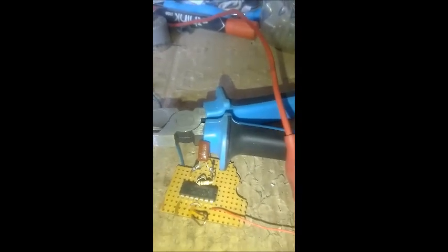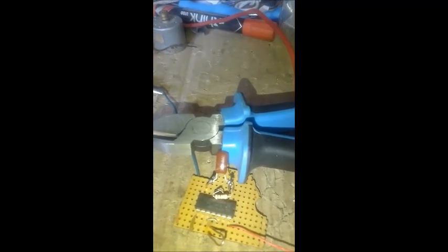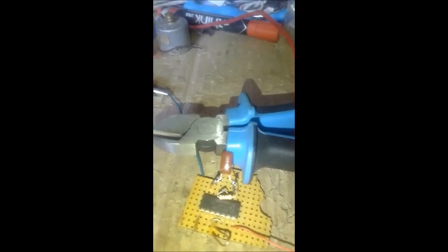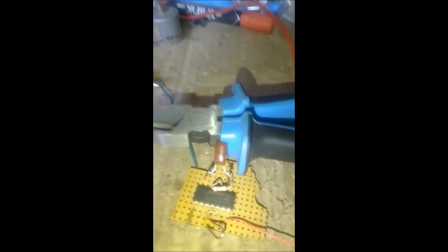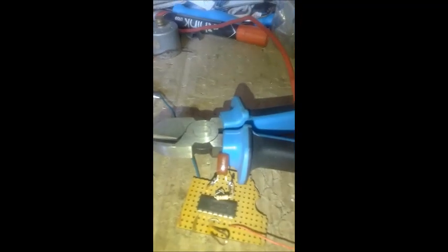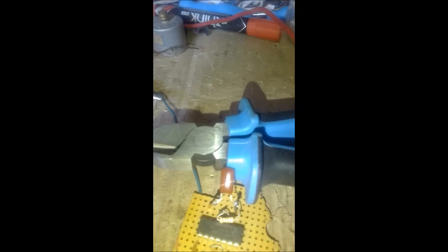Right, you have to actually bridge together the drain and the source terminals, so that you can have an increased capacitance. Okay, there are 2 capacitors, of course. If you check the literature on MOSFETs, they call them stray capacitances, but you can actually use them as a component in your circuit.